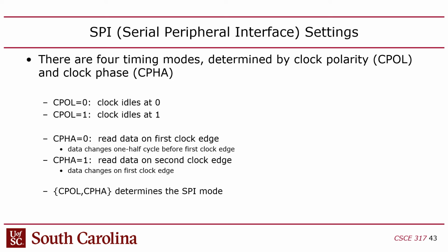Now I don't know, did you guys cover flip-flops in 211? So flip-flops are these memory elements, right? And there are flip-flops and there are latches. The difference between flip-flops and latches is flip-flops are edge sensitive. So they capture data on either the rising or the falling edge of a clock, right? And latches are level sensitive. But no one uses latches, everyone uses flip-flops, right? So with an SPI channel, you're going to use flip-flops too. And those flip-flops are sampling the data on a clock edge. Make sense? The question is what clock edge? Rising edge or falling edge, right?